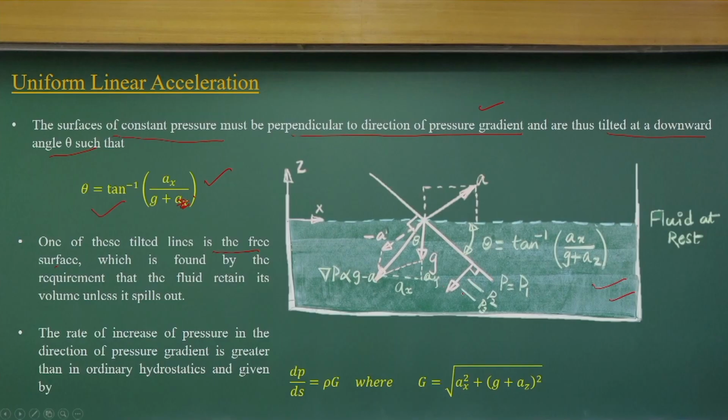But if you do not have enough wall height, sometimes the liquid can spill. For example, if the container is moving with a particular acceleration and you increase the acceleration further and further, it may reach a stage where the liquid overflows from an open tank. If you have pressurized conditions, we can solve a problem like that when I solve the numerical problems. Basically, as we move with constant acceleration, the free surface changes and the pressure diagram changes, and that is what equates the force components.